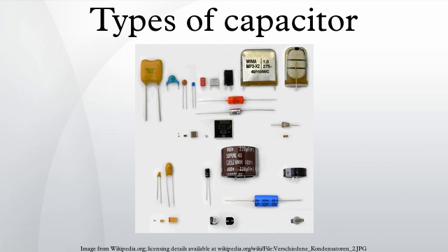Standard measuring conditions are a low-voltage AC measuring method at a temperature of 20 °C with frequencies of 100 kHz, 1 MHz or 10 MHz for non-electrolytic capacitors with CR of ≤ 1 nF, 1 kHz or 10 kHz for non-electrolytic capacitors with 1 nF < CR ≤ 10 µF, 100–120 Hz for electrolytic capacitors, 50–60 Hz or 100–120 Hz for non-electrolytic capacitors with CR greater than 10 µF. For supercapacitors, a voltage drop method is applied for measuring the capacitance value.